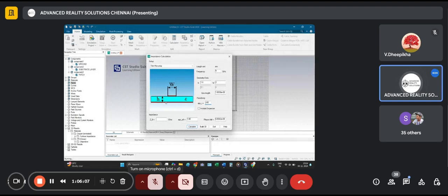Here, if I click calculate, look at this, the Z0 impedance value will be displayed. The value is 62. But the general value is that the impedance should not exceed 50 ohm. That is the standard value. How may I change it? The height and epsilon r are fixed. I can only change the width. I will change it to 3 and calculate again. It's getting closer, so I should reduce it. At 2.9, I get 50.81. This is okay.